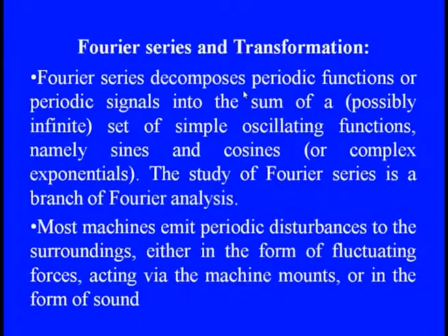The Fourier series decomposes a periodic function, and that is one of the biggest drawbacks of the Fourier transformation: if we have a non-stationary waveform, in which the statistical parameters of the wave vary, the fast Fourier transformation always gives misleading information. This is the drawback; otherwise the Fourier transformation is the best way to see the defective frequencies, or the frequencies dedicated to the entire exciting zone.